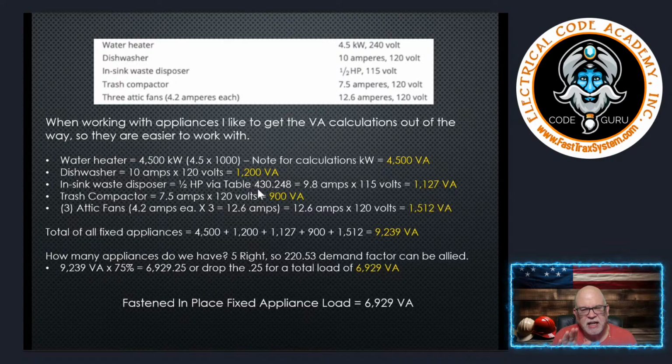Remember this: anytime you get a horsepower rating, even on the exam, the first thing you want to do is convert this to VA because I'm going to be working with VA. So you have to find the FLC. The FLC for this one is found in 430.248, because this is single phase. If you go there and look, you'll see that it's 9.8 amperes.